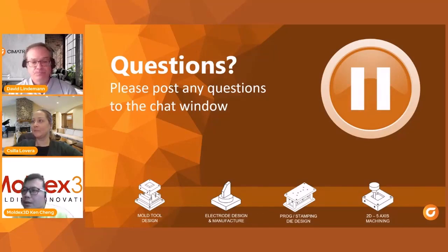Yes. So basically, we do have a function that could give you the best gate location. However, some areas, due to surface quality, you probably don't want to gate in. So eventually, you still need to do a quick flow simulation in order to understand where the best gate location is. So you are able to use the simulation results to discuss with your customers or molders to see if you could choose that area for the gate location.